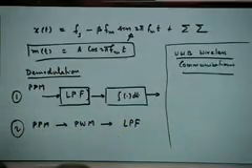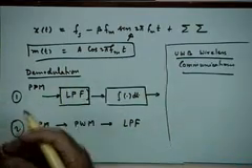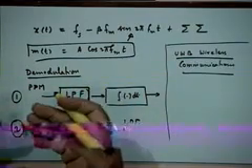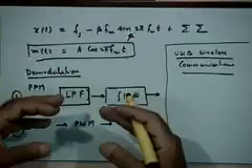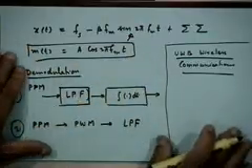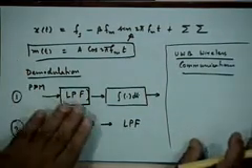They are ultra wideband, and therefore the signal level is so low that somebody who wants to intercept it cannot see it. That's one advantage of that. The average spectrum floor is very low. So these have become very important of late, and a lot of research is currently happening in this area. And when you do this, since you are transmitting baseband pulses, information in them can be embedded either through amplitude modulation, or pulse width modulation, or pulse position modulation. Right? So I thought some of the modern flavor about these pulse modulation schemes I should just briefly mention before we close this topic.